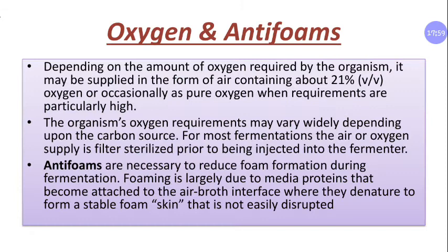Oxygen and antifoams. Depending on the amount of oxygen required by the organism, it should be supplied in the form of air containing about 21% oxygen, or occasionally as pure oxygen when requirements are particularly high. These oxygen requirements may vary depending upon the organism used and also the carbon source used. For most fermentations, the air or oxygen supply is filter sterilized prior to being injected into the fermenter.